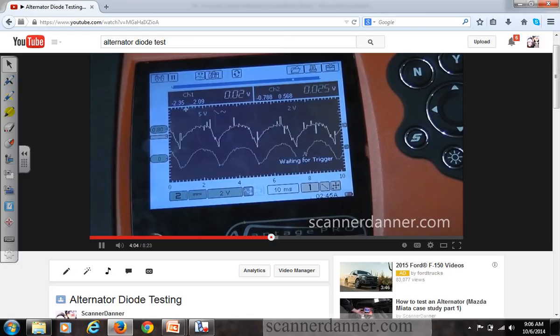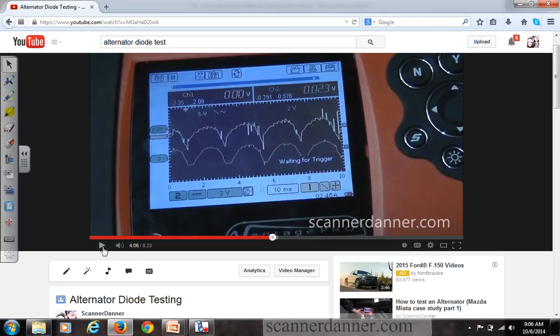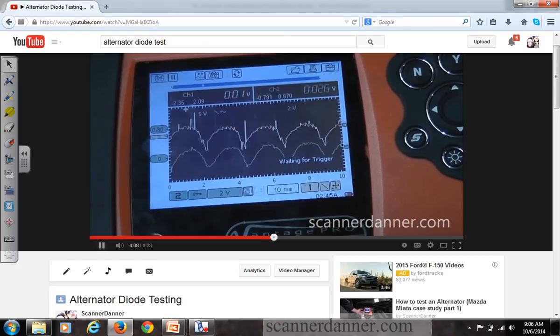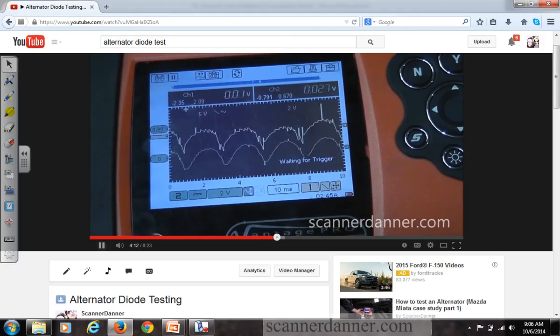is that one at the battery? Hang on. Is that the battery? The output speed of that sensor, there's no signal there at all until the wheels start turning. Okay, so the trace underneath it is my output speed sensor, my vehicle speed sensor. Same exact thing. Why is the speedometer reading 20 miles per hour when the car's not moving? Bad alternator. Cool? Just another thing you want to put in the back of your mind.